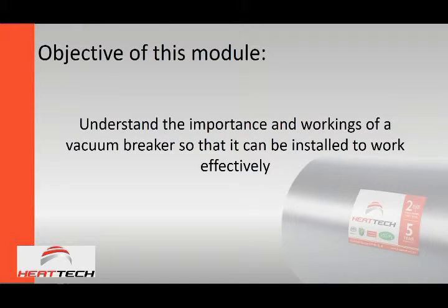I have seen various installations where it was clearly quite difficult, with space constraints and all sorts of things that make it difficult to install the system as the book says. But I've also seen areas where vacuum breakers have been used incorrectly. If you don't understand how it works, you might be inclined to think that it doesn't matter how I install it as long as it's there. It can actually make a difference and make it not function correctly.